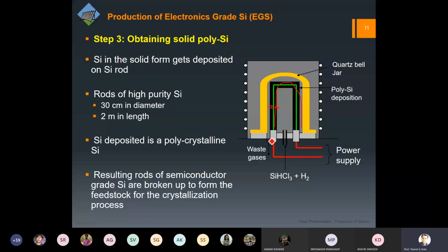It is in the shape of a rod, and this is not good for us for making the wafers. And the most important point is that when this deposition is done, the silicon goes and sits randomly. It is something like when you enter a hall, especially a class, you go and sit in the last row, right? So something like that, and then people start sitting here and there. It is very much random, and that's why the orientation of the silicon is not in a proper manner. So instead of having a monocrystalline crystal structure, what it forms is the polycrystalline structure.